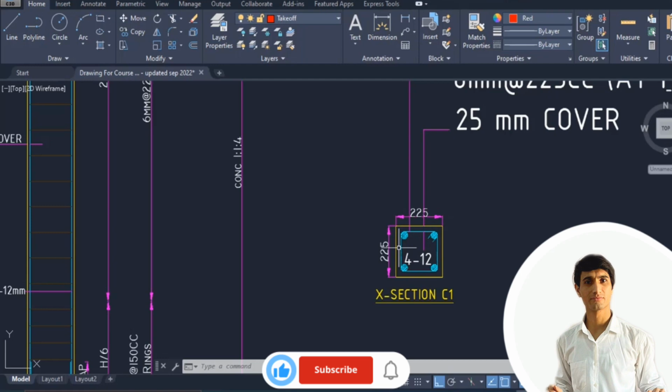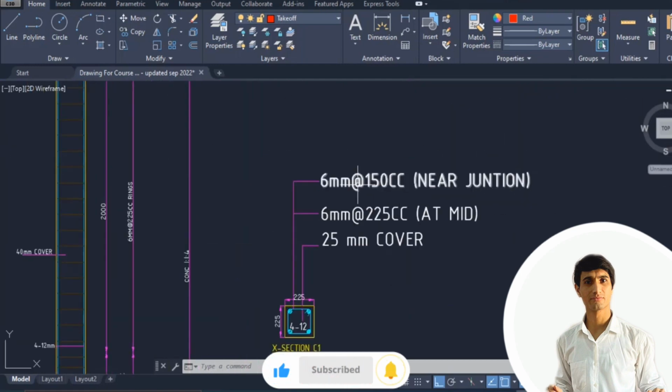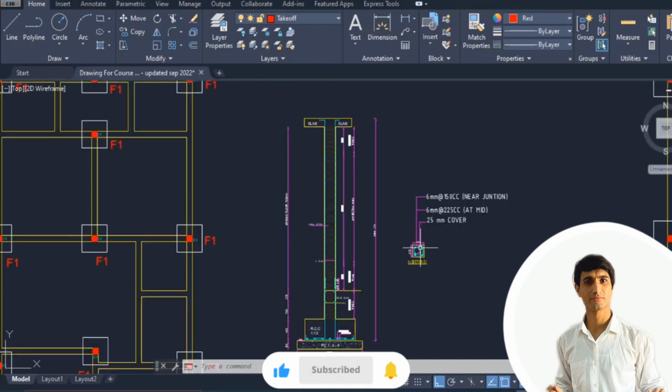Cross section is 225 by 225. It is mentioned that we are using 6 mm rings at 150 center to center near the junction, and at mid we are using 225 center to center. Let's look at what these are, the junction and the mid. And cover is 25 mm.